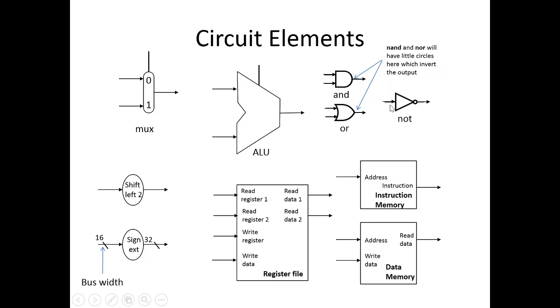And by the way, we can simplify this, and usually just a little open circle is used. So if you want to turn this AND gate into a NAND gate, or NOT AND, you just put a little circle in front of it. If you want to turn this OR gate into a NOR gate, or NOT OR, you just put the little circle out here. And if you want to invert any of their inputs, you just put the little circle there, okay?